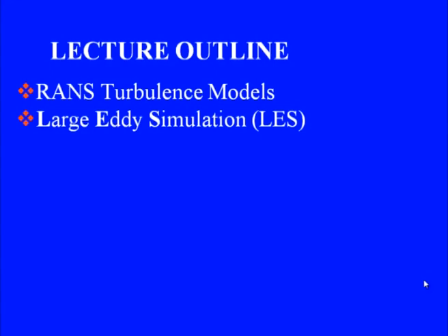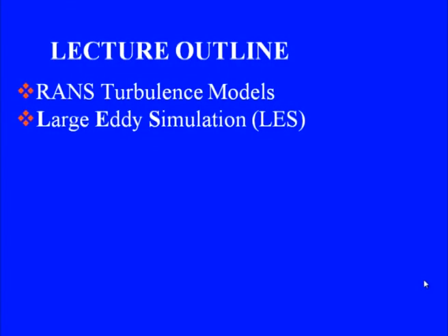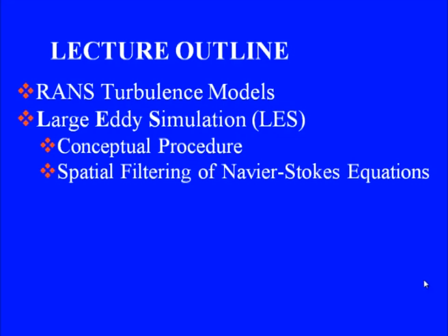So, the focus for today's lecture is RANS turbulence models, and in the second half of the lecture we will consider large eddy simulation. The outline of today's lecture: first we will look at RANS turbulence models, and then at large eddy simulation, called LES in short. We will discuss the conceptual procedure involved in large eddy simulation, then briefly discuss the spatial filtering operation of the Navier-Stokes equations for incompressible flow, and then look at one or two popular subgrid scale models for large eddy simulation.